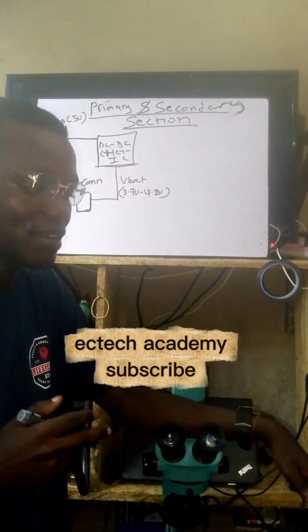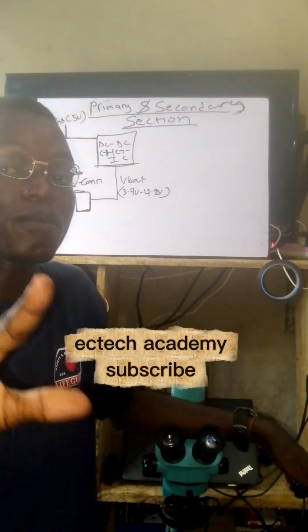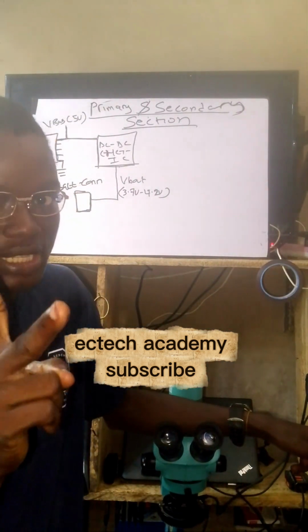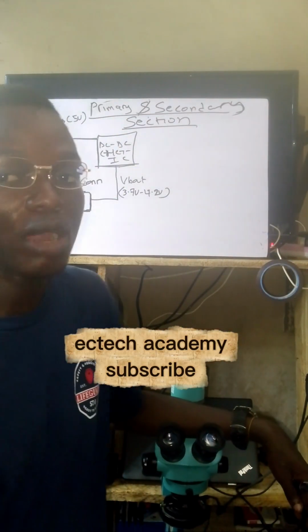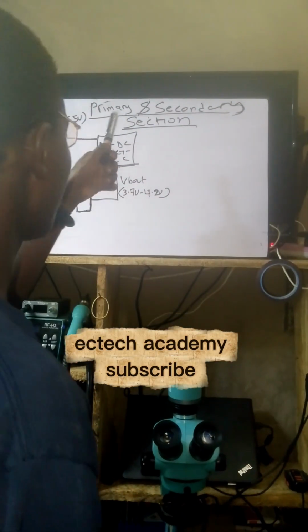That slave charging IC is responsible for giving out VPH power. That's for the latest mobile phones. In such a phone, we have two charging ICs, but one will be working to give out VPH power to the system, while the other one is required for charging and some other purposes. But notwithstanding, I'm going to combine everything at once.